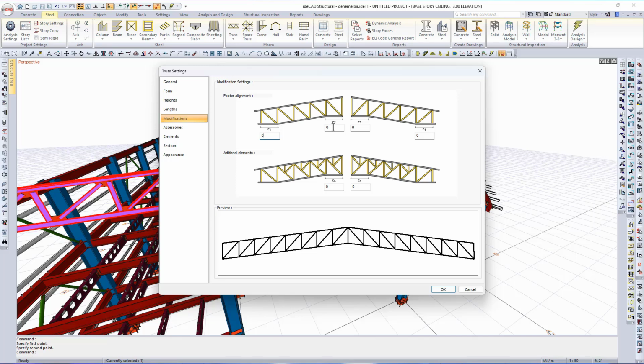In this tab, you can designate these flat panel areas by specifying numbers from C1 to C6. Please note that these parameters represent the count of panels, not their lengths. This is a common source of confusion, so be careful. For clarity, I entered 3, which refers to 3 panels, not a distance.